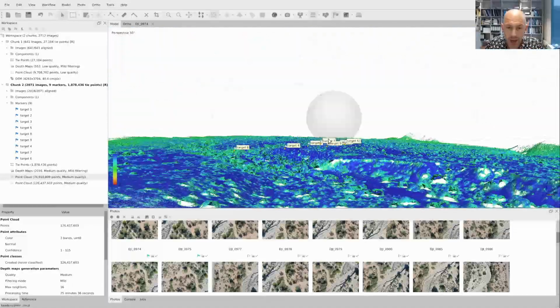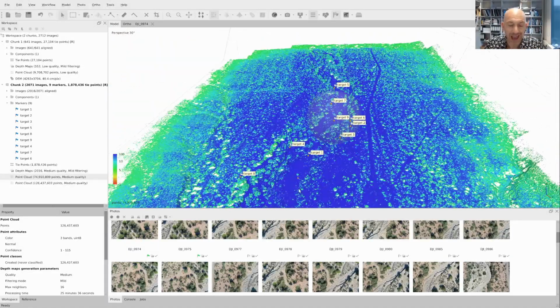But right now we have a point cloud that is first of all smaller. We have not removed any of the ground points. The ground is still very well depicted, but we have removed points that are related to vegetation or points that are not that well constrained. So if you are just interested in creating a digital terrain model, so depicting the solid Earth surface, then this is a reasonable filtering step. If you're interested in vegetation height and other ecological parameters, then you definitely don't want to do that filtering step because you're removing the precious vegetation from your data set.